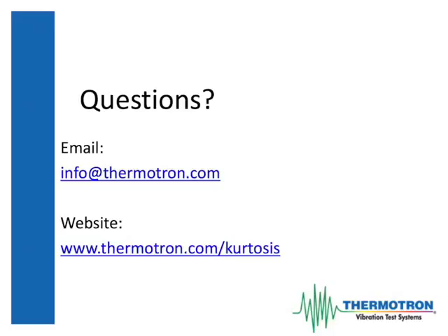Next question. You said kurtosis derates the shaker, but doesn't it really just derate the amplifier? Couldn't someone add additional amplifiers to make a shaker that didn't have to be derated when it ran kurtosis? No, actually, that's a really good question. In theory, yes, there are arbitrary shakers where you could do that. In practice, well-designed shakers tend to run out of current and voltage at about the same time. Now, obviously, that's a very general statement. Under typical loads, well-designed shakers typically run out of current and voltage at about the same time.